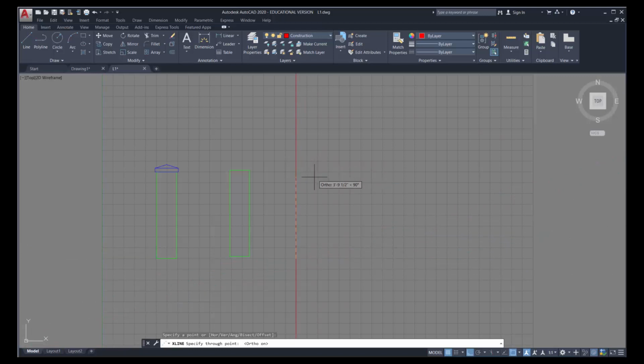That specifies perfect horizontal or vertical lines. It's called the ortho command, and it's a drawing aid. And the nice thing about it is when I click my second point straight up and I move my mouse to the right, it now does a horizontal line from the same point I started. Press Enter, and then F8 once again. Now that may have been confusing. You may have to try it a few times to really get a handle on what that command can do.